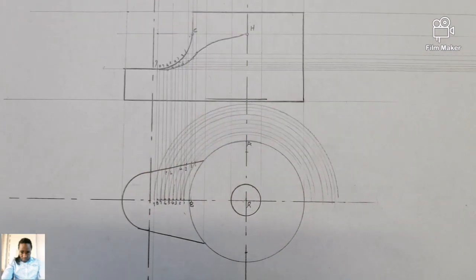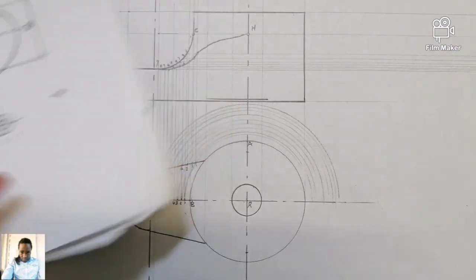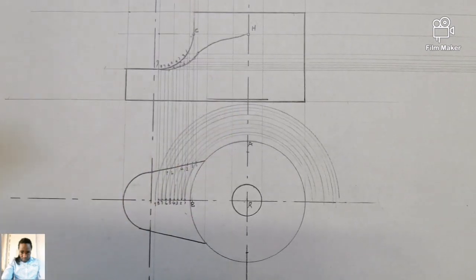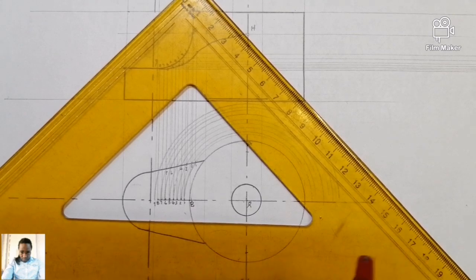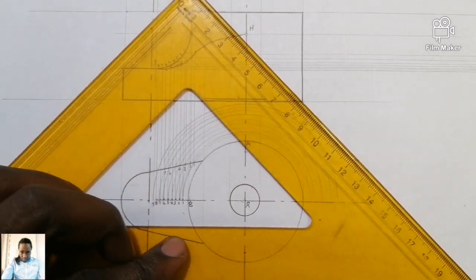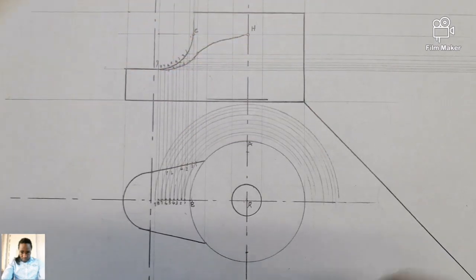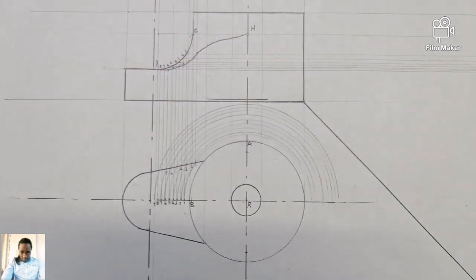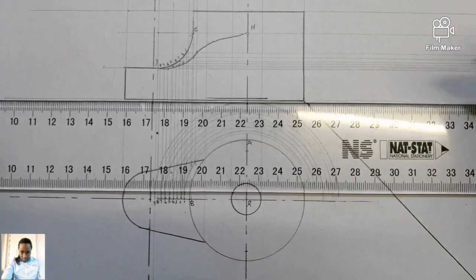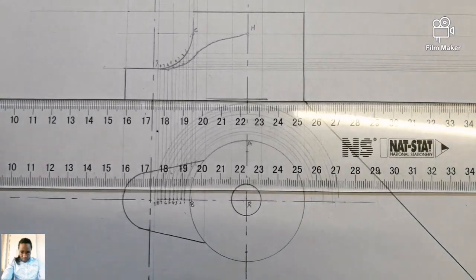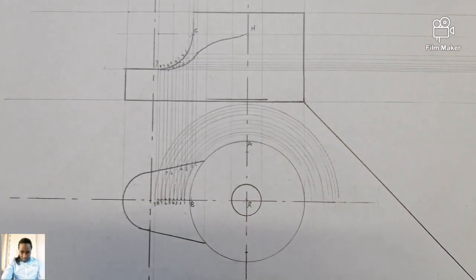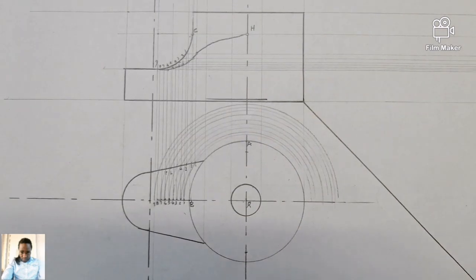They didn't ask you about the left view. So you can leave your work like this, because for the left view you would have a solid dark line like this, then construct your lines so that you have your left view in this direction. But they didn't speak about anything left, so you can submit your work like this.